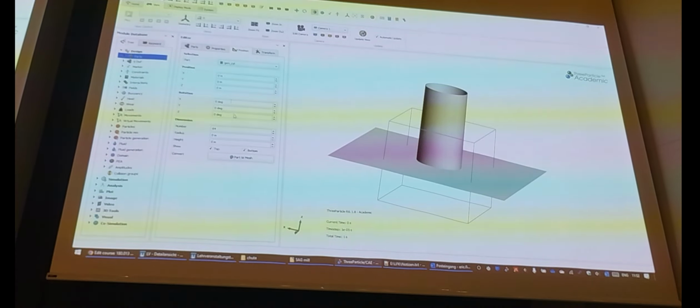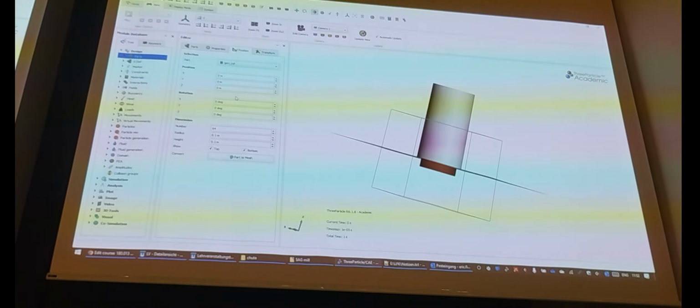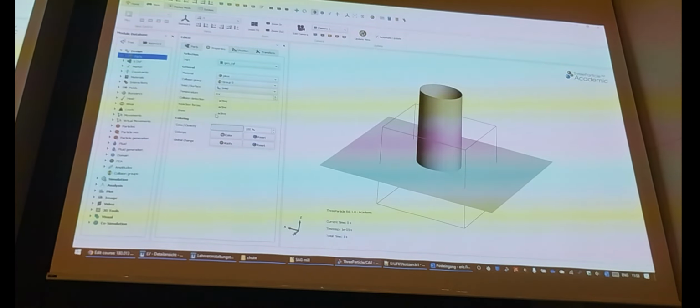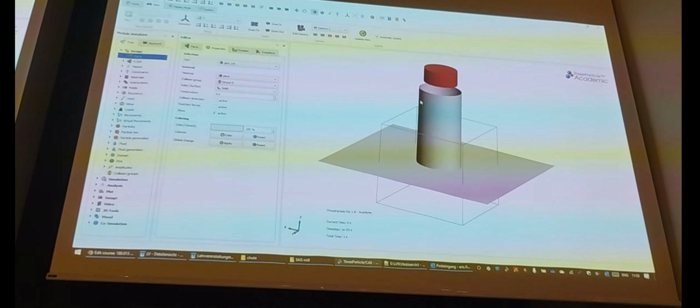I will just do it. So set position a bit higher, like here. Yep. And you can use that as well. You say, okay, a little bit, something like that. But you need to define that this cylinder is not collision detected. So you need to turn that off, and then it can be used as a generator plane as well. You can also say that it is not shown, but we can try it with that if you want.